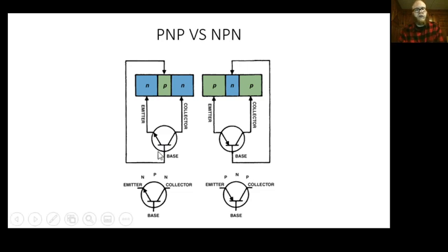When I start flowing current through the base, now all of a sudden the distance between the two isn't as great, and this actually starts to become saturated, meaning current is flowing through it, electrons are starting to do their thing, and it allows this larger current then to overcome that barrier and start flowing as well. All right, so it's like we would have a forward biased diode here, and that allows these two N-type materials basically just to bypass the P material at that point.